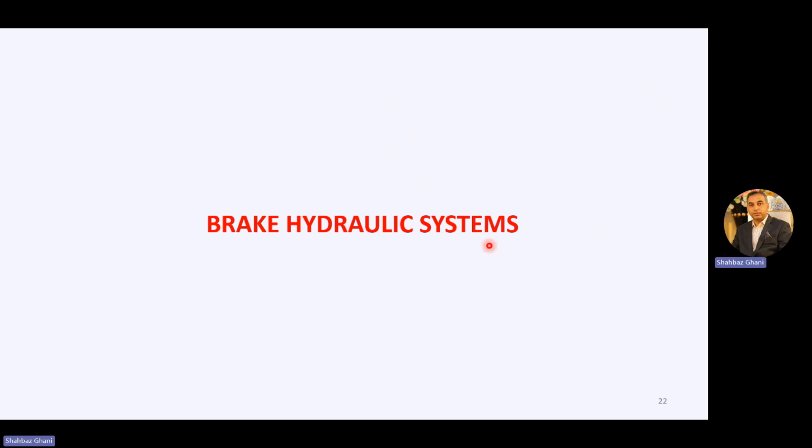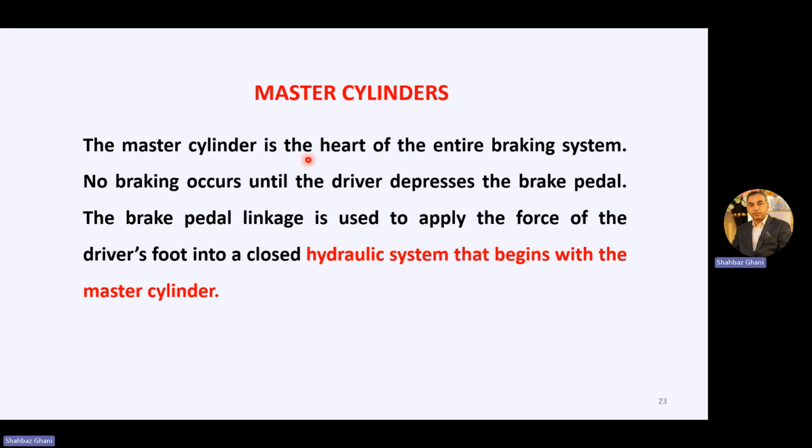Brakes hydraulic system. The master cylinder is the heart of the entire braking system. No braking occurs until the driver presses the brake pedal. The brake pedal linkage is used to apply the force the driver puts into a closed hydraulic system that begins with the master cylinder. No braking occurs until the driver depresses the brake pedal.